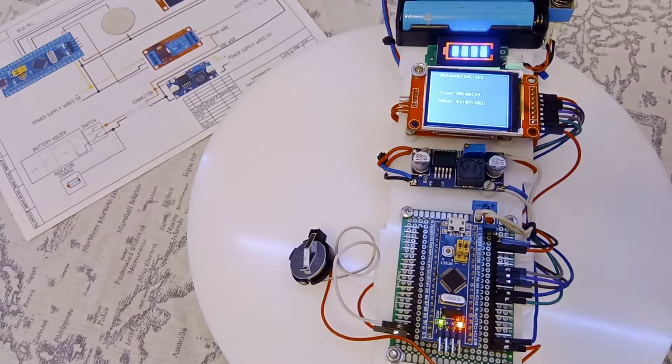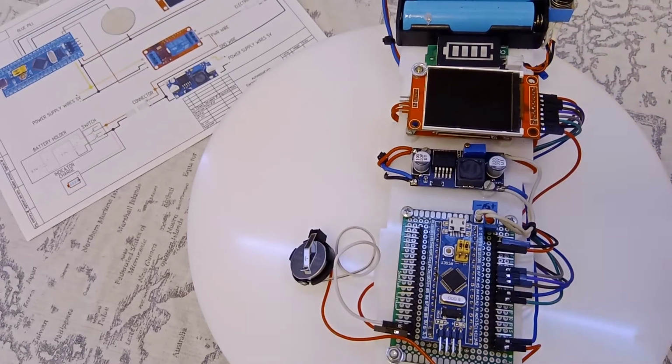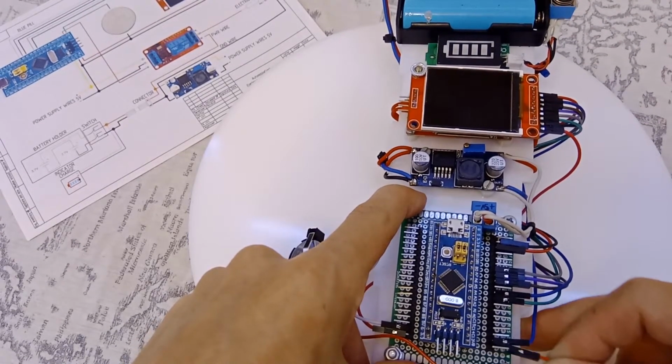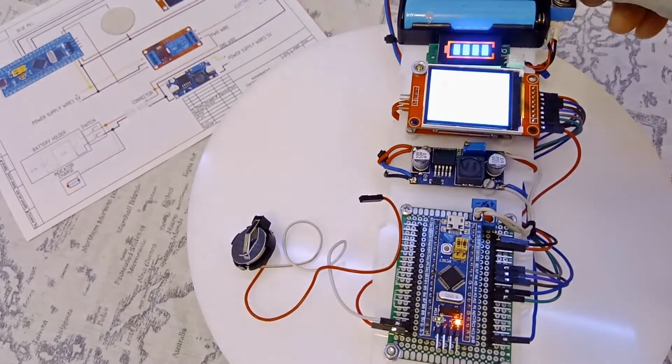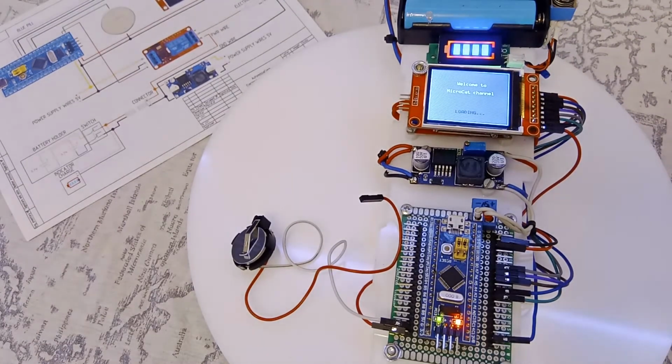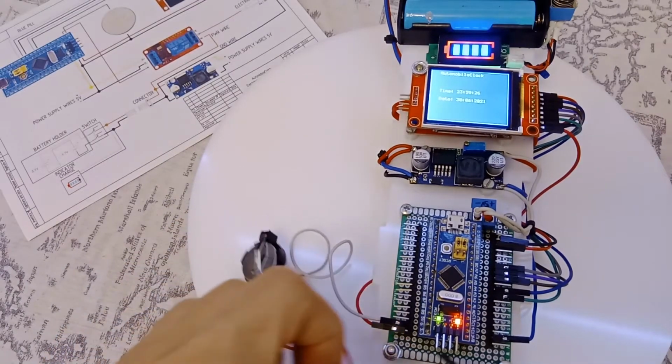Now turn off and unplug the battery. We see a long load of the controller. This is a waiting cycle for the start of the watch quartz. As you can see, the time and date are lost. Thus, a prerequisite for the operation of an RTC module is the presence of an external battery. Thus, power will always be supplied to the module.